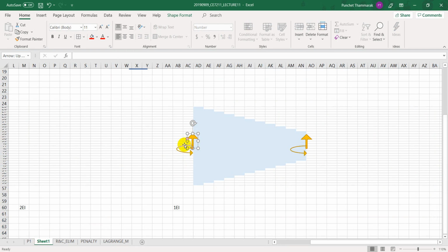So this is a concept we use to come up with the stiffness matrix. We have one beam element at the second class. We displace the node, first node, to 1 unit deformation U1. You keep other degrees of freedom stationary, they are all 0. Then you get the corresponding force, moment.